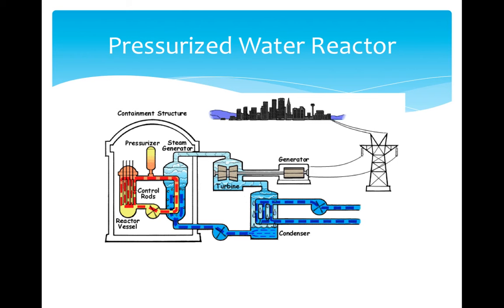The design of a PWR is distinguished by having a primary cooling circuit which flows through the core of the reactor at high pressure and a secondary circuit in which steam is generated to drive the turbine. The number of loops each reactor contains varies depending on the purpose or the type of PWR being used. The loop is considered to be on the primary side of the reactor, which in some cases will contain a coolant pump and a steam generator, although this is not always the case. A PWR also includes anywhere from 150 to 200 fuel assemblies, which are arranged vertically in the core.